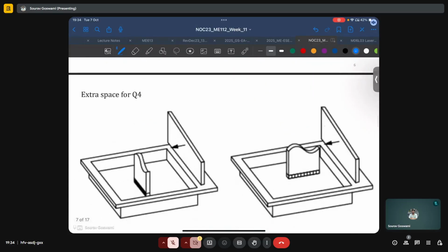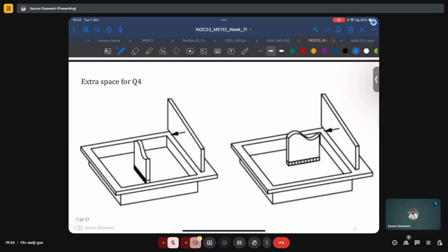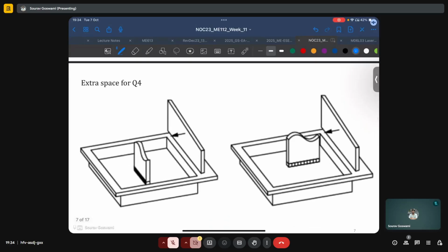And I also have the optimal solution here. So at the bottom we have the support structure to allow for machining allowance while separating this part from the build plate. And then we have reoriented it such that we minimize the number of edges which are parallel to the recoater blade, and this is the total length of the edges which are parallel now. And also we minimize the surface area of the part which is in contact with the recoater at any given time.